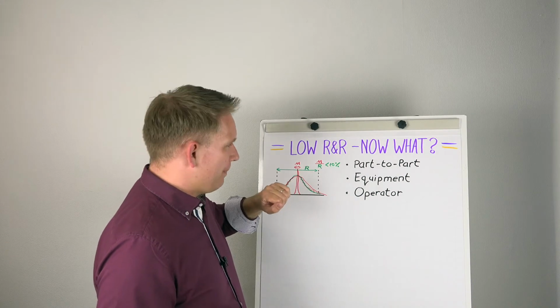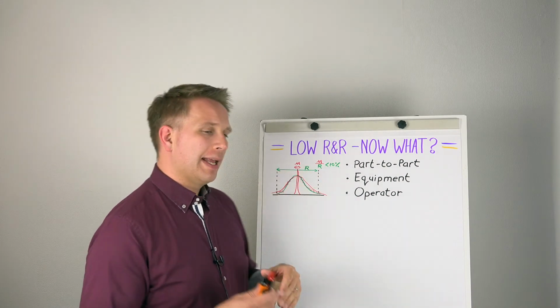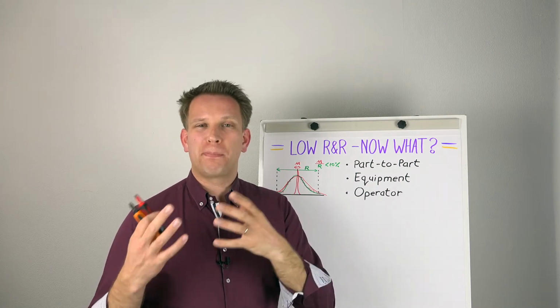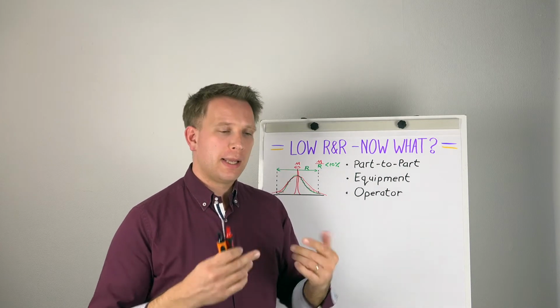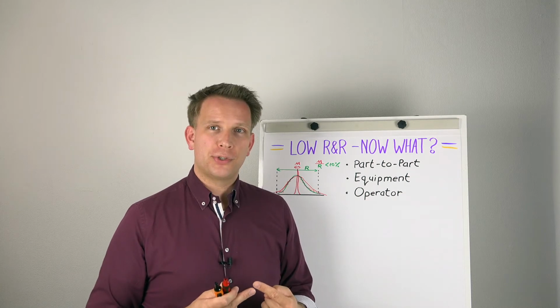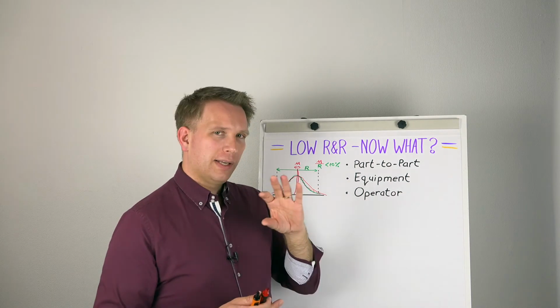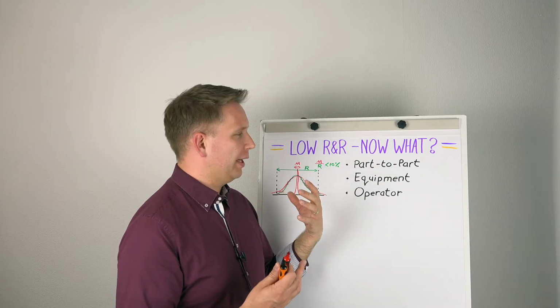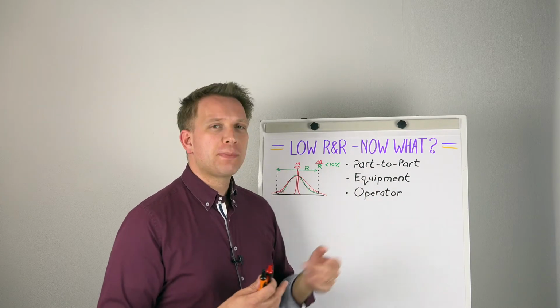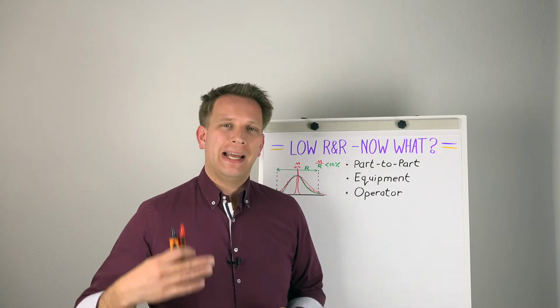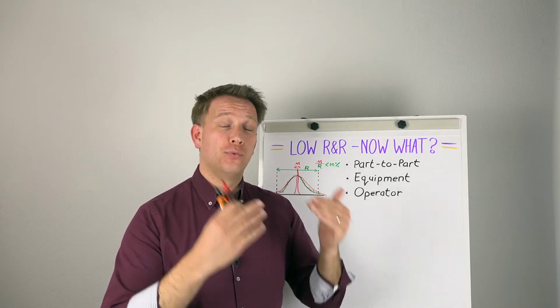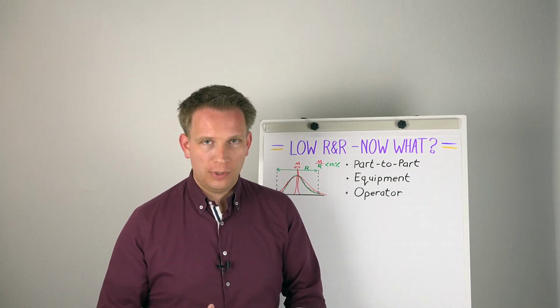In the same way, we also see if you repeat each measurement, so each part measurement 3 times, but you have 10 parts also, you can see that one part gets measured 3 times by the same operator, but the difference must be more in the equipment. Now, of course, it can be that an operator just very poorly reads the equipment, cannot work with the equipment.